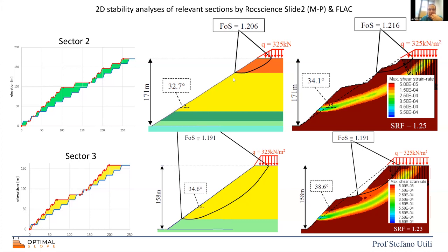But in sector 2, where there are more layers, it's a bit concave, then convex. This is just to say that the optimal shape really is a result of calculations, and cannot just be extrapolated from one mine to another, because it depends on the physical and geotechnical properties of the layers and their stratigraphy.